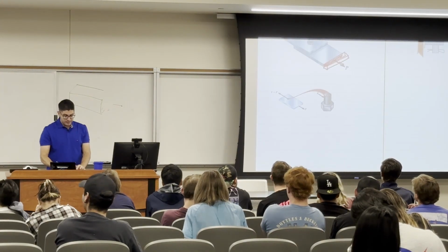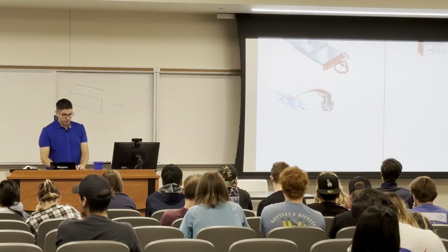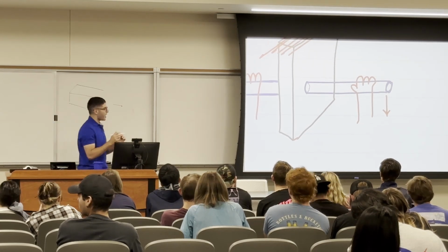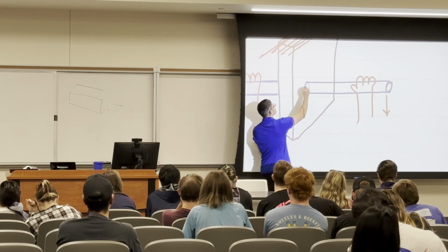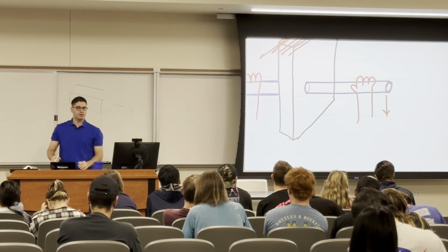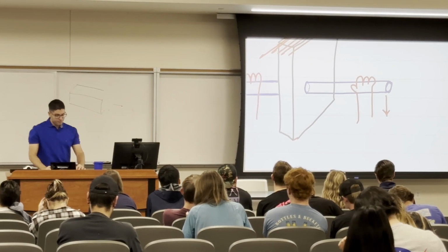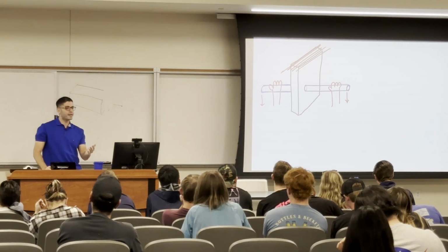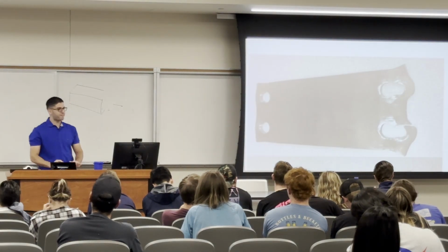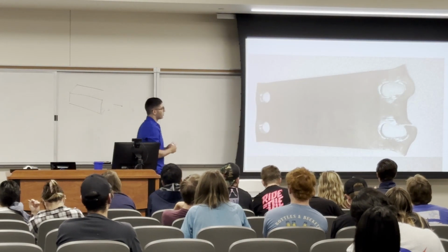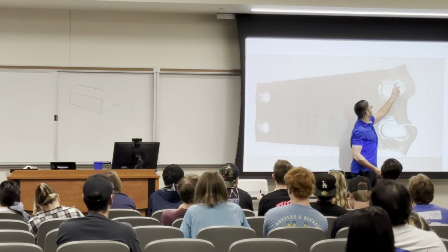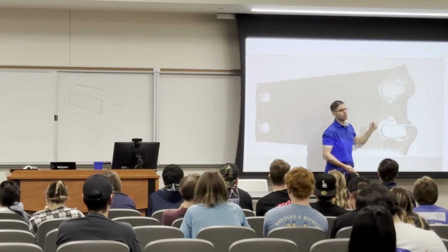So now we said that this load in the normal stress is distributed over the whole area. What about this? What area is my load supported by, the whole cross section or the contact of the rod with the plate? What do you think? Okay, if you're still confused, let me show you how it's going to fail so that you would understand how it's going to behave. So this was the failure of this. Which area supported the rod? Is it the whole plate or the interaction of the rod with the plate?